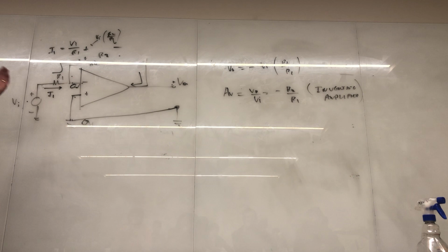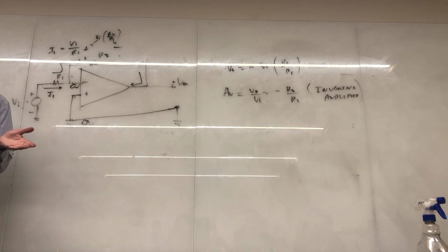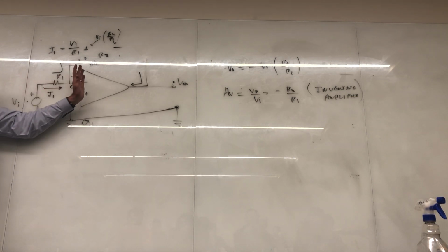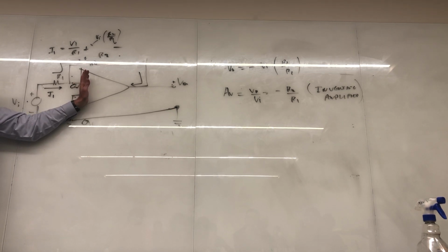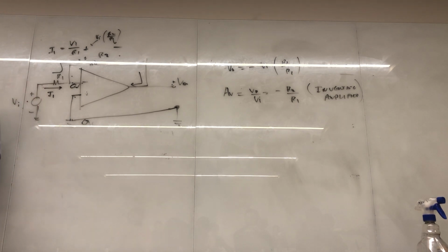Now remember, the input impedance of this, and this is down the road, you can make this thing to be something where basically, by the ratio of resistances, because the input resistance here is extremely high. You can make R1 100,000 ohms, for instance. Follow me? Once you have that, no current flows into that effectively, all right? But that's another thing. Anyway, this is usually the first stage of amplification in a power amplifier. Now there's other stages that come, and they don't have to always be op amps, and I can't get into all that. But this is the simplest and the first stage of amplification for most low frequency circuits.